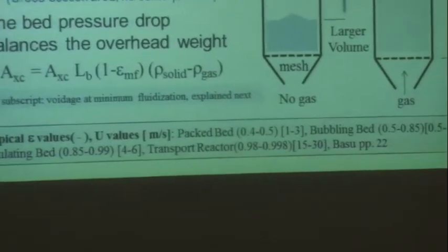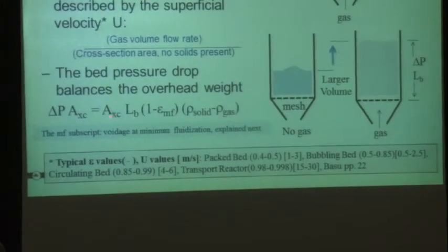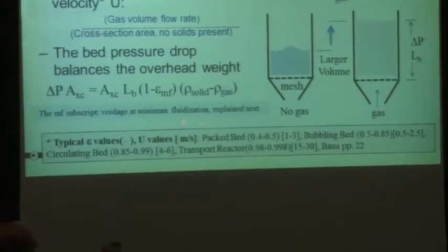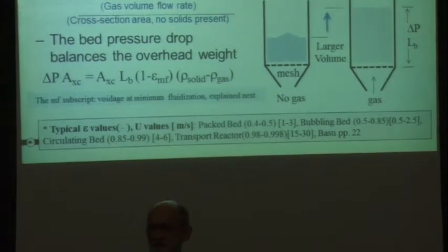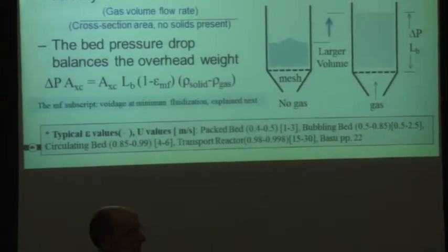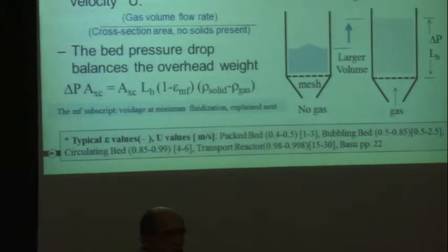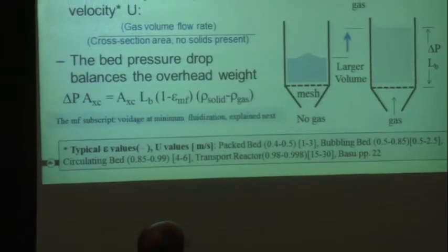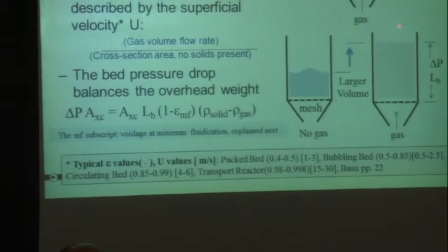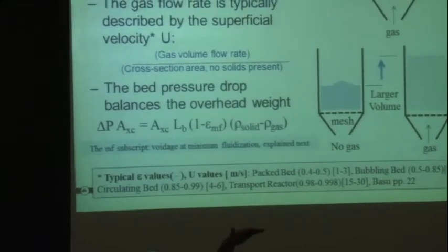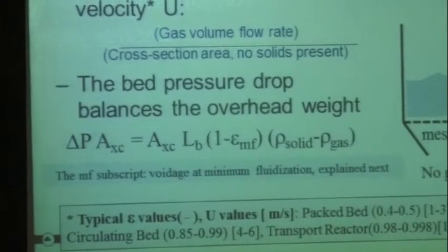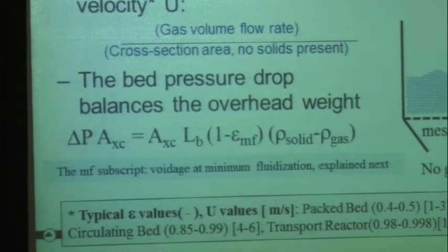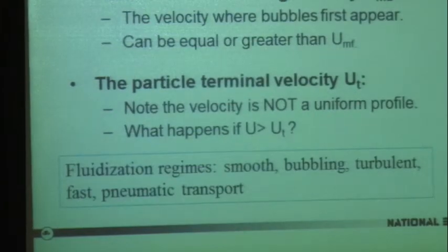Oh, wait a minute, I wanted to mention on the bottom there. One of the most helpful things you can remember from today's lecture is, how much pressure drop exists across a fluidized bed? You have to lift the bed and support it by the airflow. And so it's a very easy calculation. The pressure drop has got to equal the mass of the bed material. It's that simple. You can look through the equation there, but it's just a very simple thing to remember, and you'll understand how you get the pressure drop.